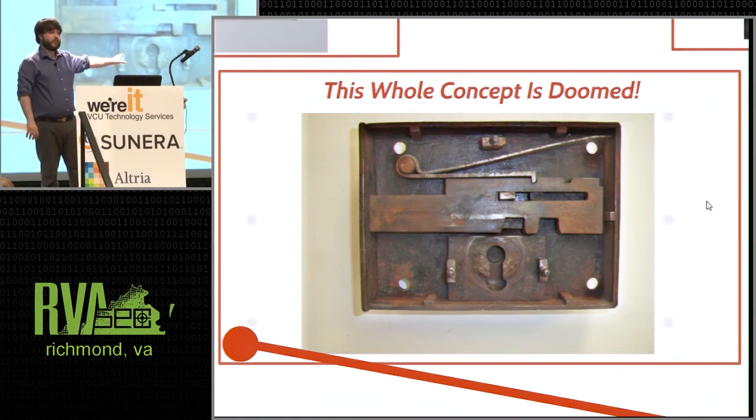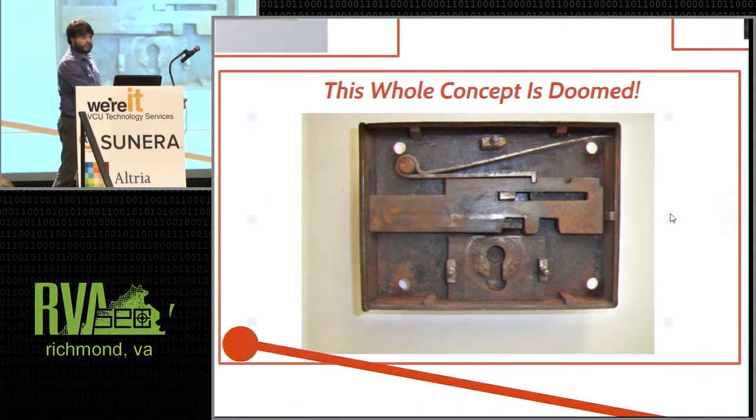Previously, the key has always acted directly on the bolt. Now, the key still will act directly on the bolt, but it is also going to have to lift that lever against the spring. The two notches that you see in the bolt are revolutionary. This is an amazing inflection point in the history of security. And I have a Barron-style lever lock back at the village if you want to play with one tomorrow.